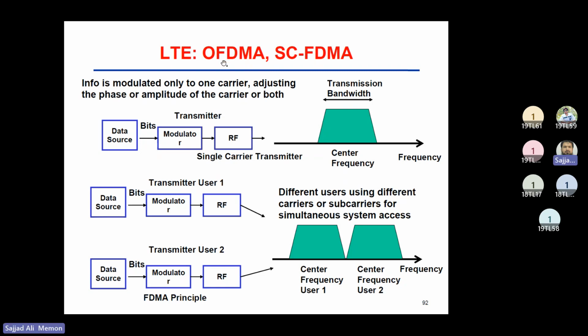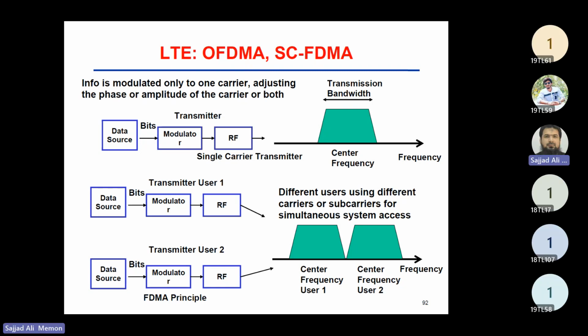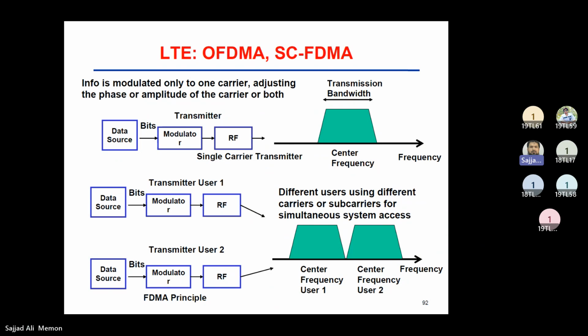Multi-carrier means we modulate our data over multiple sub-carriers rather than transmitting it over a single carrier. The advantage with OFDM is that if any one of those sub-carriers gets serious fading, then only that information will be lost. Other information will remain intact and can be received correctly.